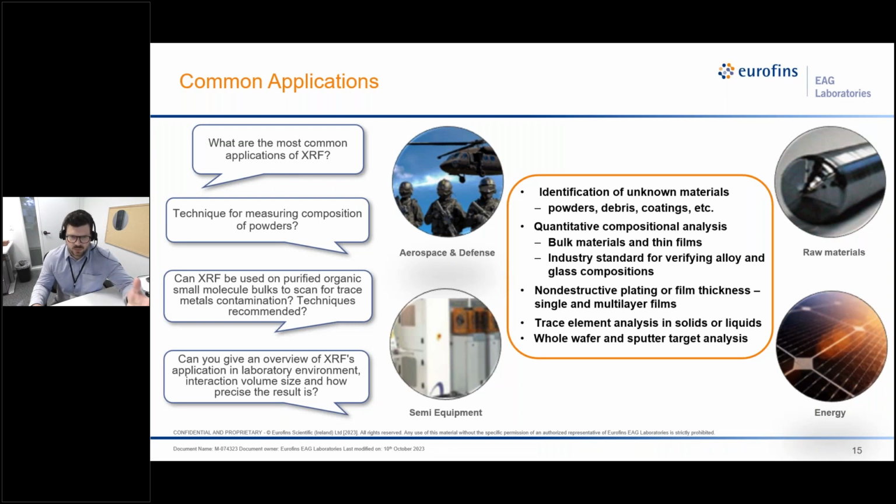The XRF instruments we have in-house here can analyze spot sizes from 0.5 millimeters to 30 millimeters in diameter, with larger spot size giving us the most sensitivity. So if you guys ever have a question on how much sample you should send us, we recommend always erring on the side of more so we can get those detection limits you may be looking for, if that's possible. We also have a sample adapter for large, oddly shaped parts available.